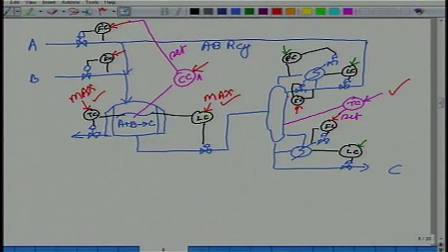You can think of it this way. Let's say A and B are initially balanced, exactly 100 kilomoles per hour. I give A a pulse of some duration. So B is fixed at 100, A went from 100 to 110 for, let us say, 1 hour. That extra 10 kilomoles an hour did not drop out. Where did it go? It went into the recycle.